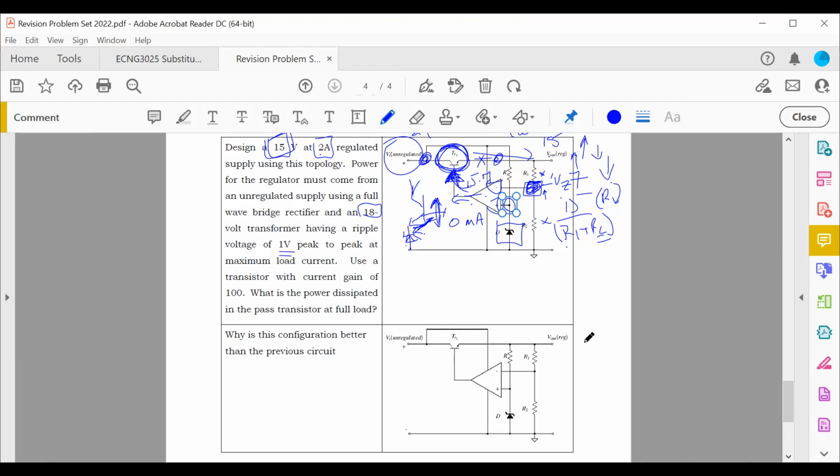That would make sense because the V will be the 15 volts and the Zener will be the 7. So 15 minus 7 over the current going into the Zener. If it's 5 milliamps and so on, and that is it. So I guess it's just the overcurrent protection stuff I think I have to learn. Yeah. And that'd be it for power supplies. And that is it, yeah.